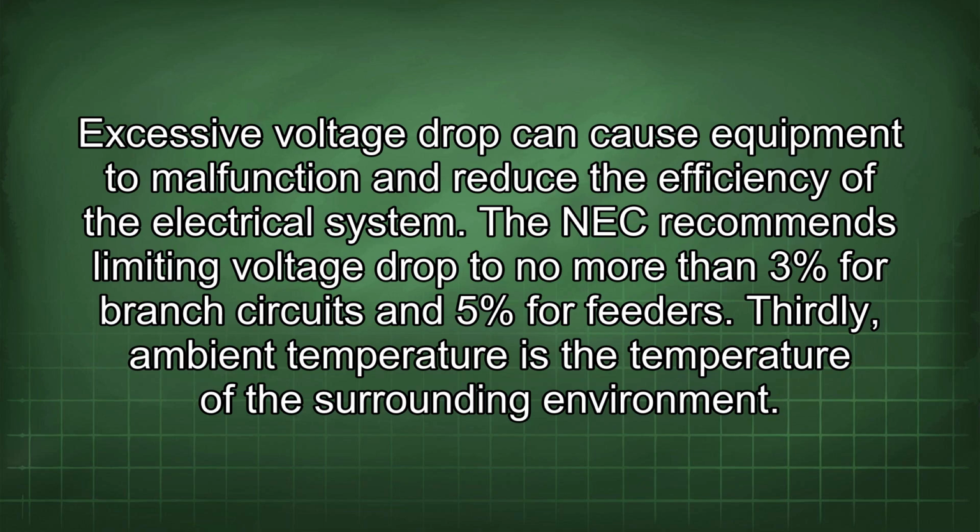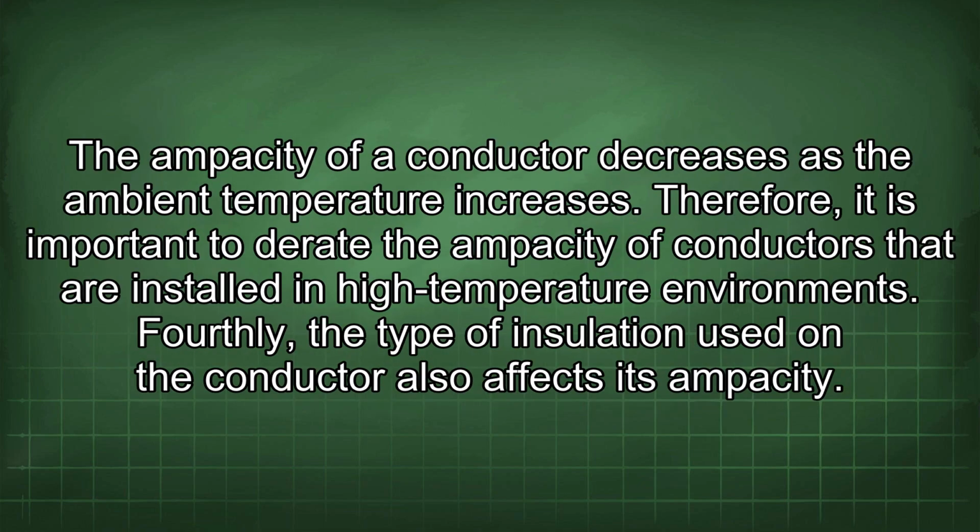Thirdly, ambient temperature is the temperature of the surrounding environment. The ampacity of a conductor decreases as the ambient temperature increases. Therefore, it is important to derate the ampacity of conductors that are installed in high-temperature environments.